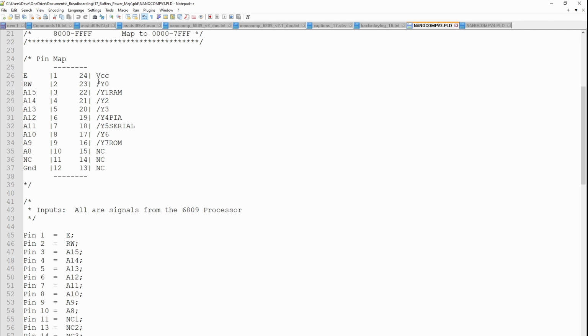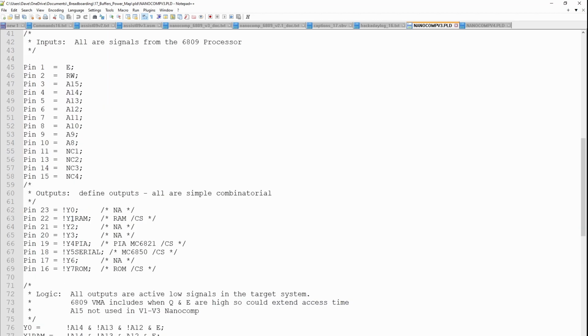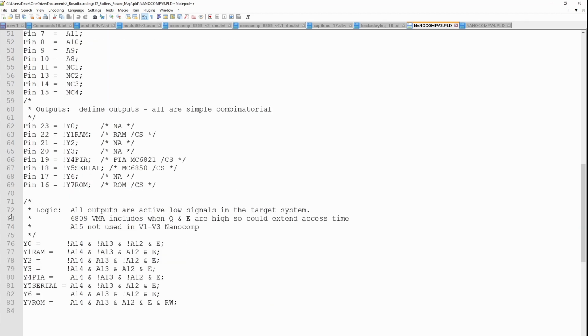And then all I've done at the moment is just simulate the 74138, so all of the output pins Y0 to Y7. So it should mean that we can just wire these up pretty much as the existing chip is. And then we define for the inputs what the labels are that we're giving to each pin. And then down here, this is really where the clever stuff occurs.